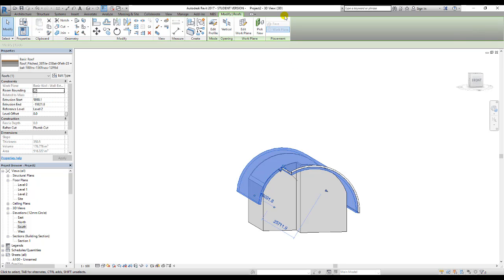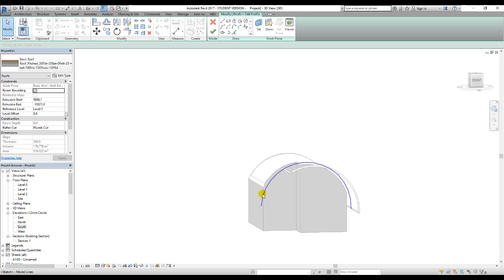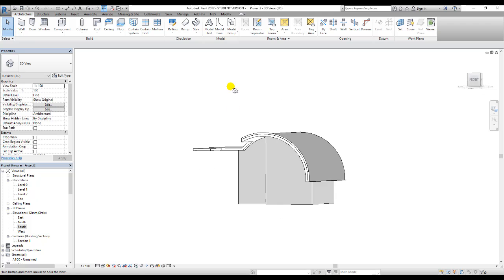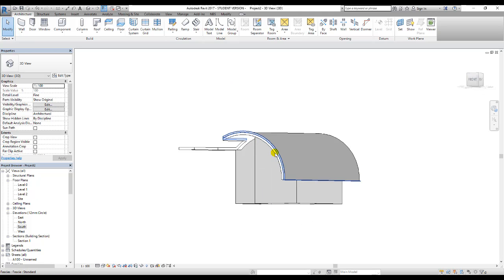Okay, I'm not going to spend time doing this roof by extrusion, but if I did want to change the profile, maybe I wanted it to come out this way. So just draw that instead, and then use the trim command. So trim there to there. Okay, that's that. Now we say OK to that. It's just done that now. All right. So all those sorts of things are available with the roof by extrusion. And I think that's pretty much all I wanted to go through with you.